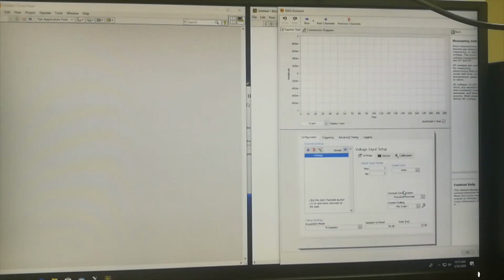I have one added thing in this setup for the pressure transducer: I need to go to the device and select the coupling mode as DC, not AC, which is not available in the vibration measurements. Okay, and also in the settings, I need N samples. I should be acquiring only one sample on demand.